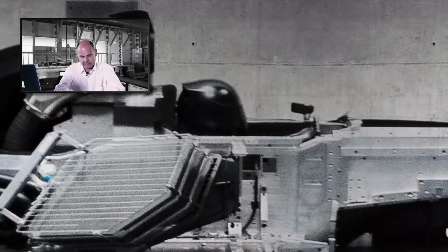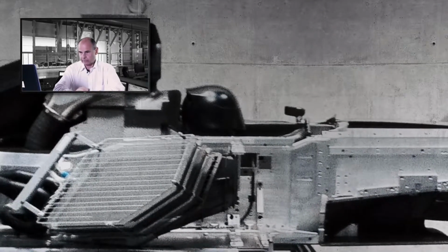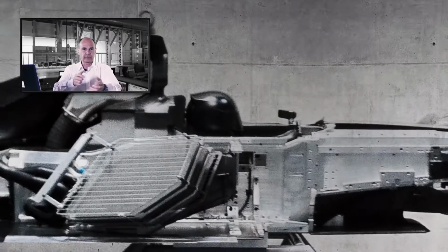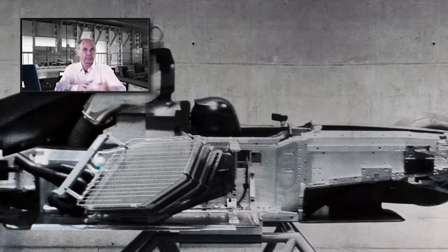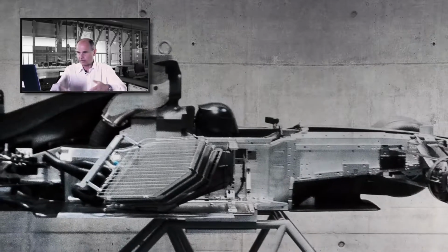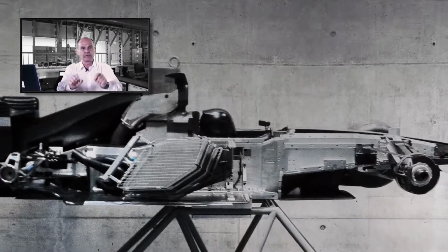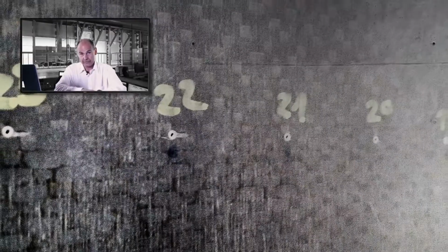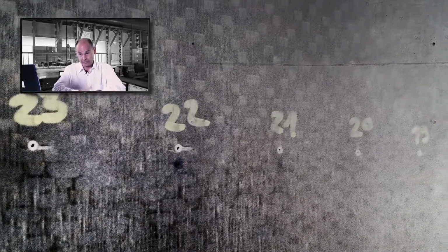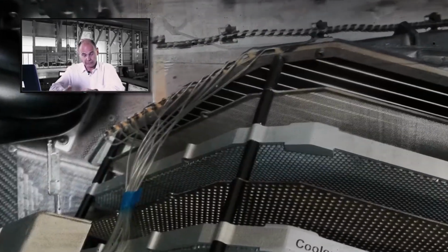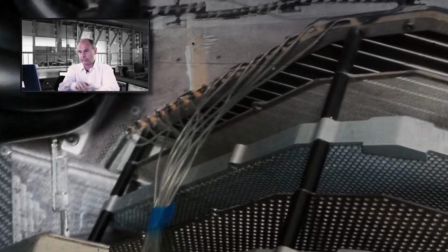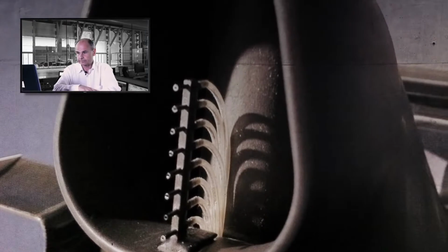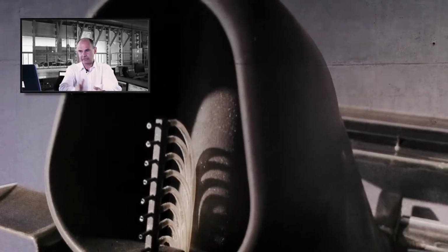And then within the model, we have lots of other measurements, position sensors. The model is a relatively sophisticated, very specialized robot, if you like. Lots of motors to move things around, for example, the steer, and then systems to measure how far the steer has moved, systems to measure pressure. We have hundreds and hundreds, and I won't say how many, but hundreds and hundreds of pressure sensors measuring the surface pressure on various parts of the model. And this allows us to understand more of the airflow around the model.